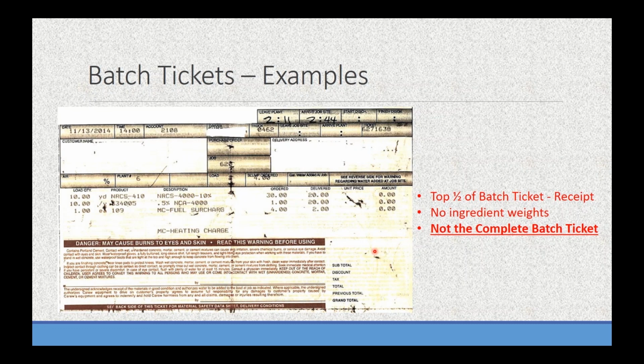It has the date, it shows the customer name, delivery address, concrete supplier. You'll see it has the mix design described. It notes that a non-chloride accelerator was used. Then you can also see that the mix was actually heated, which makes sense because the date is in November. So that's the full digital copy of a batch ticket that you might see in the field.